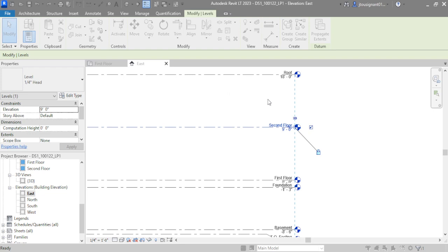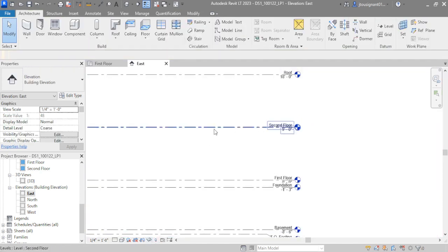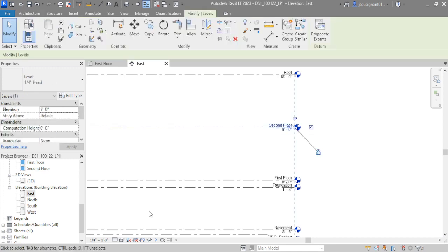This is just letting you know, hey, the consequences of you deleting this little dotted line in the elevation level are much greater than just cleaning that up. Are you probably wanting to just hide it or something? Like go into the temporary hide and hide it from the view, or you want to hide it from the view or something like that. Just so you know, deleting it is going to delete all these things.